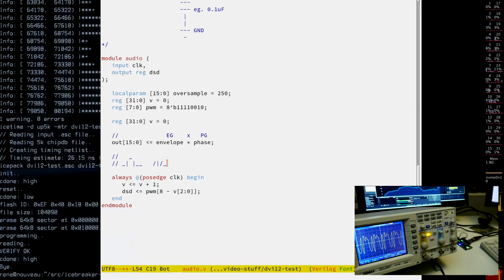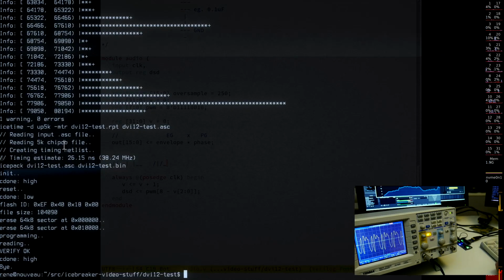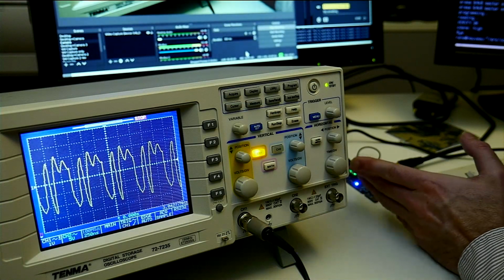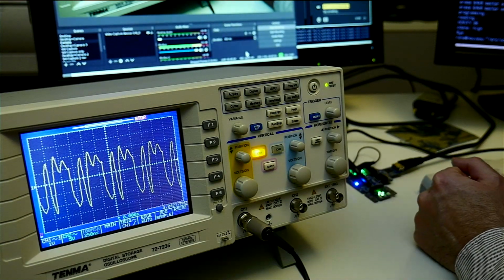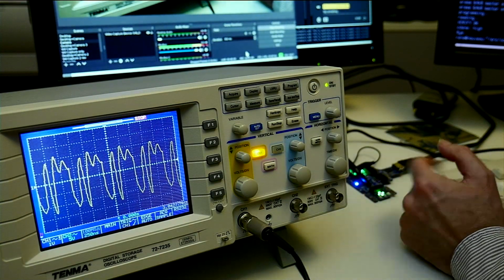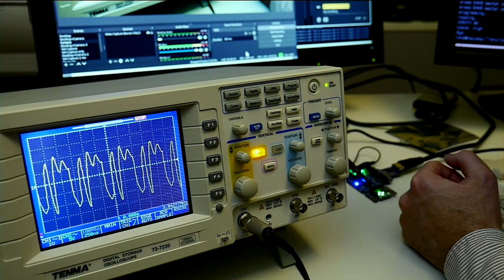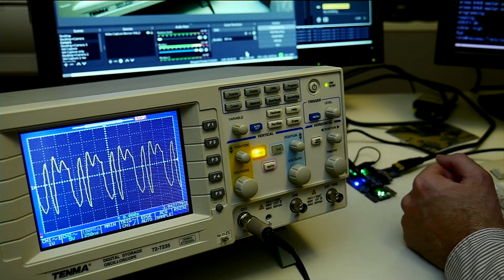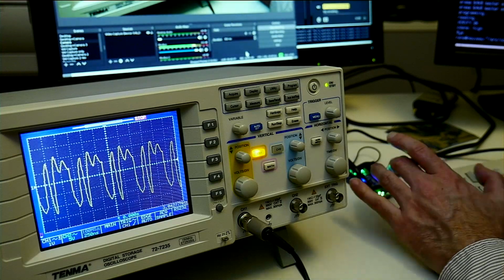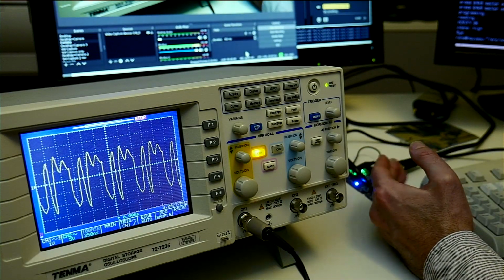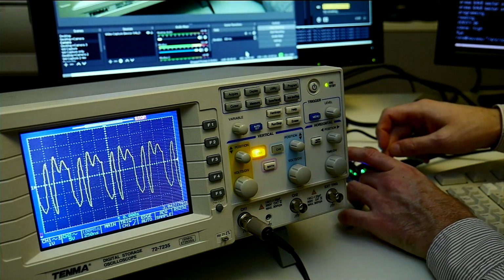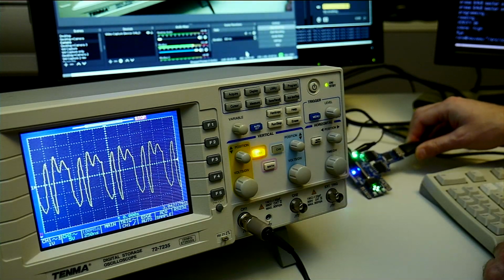We could continue a little bit hooking up here, but the thing is, if I now get out some more electronic stuff and hook up some headphone to get some sound out, of course you should not really do that too much. Theoretically, we should also have some driver, not to connect this directly to the FPGA. The NES emulator people said it's fine. They didn't burn the FPGA yet, but with a resistor it probably shouldn't overload. So probably I will solder a resistor, maybe also break off this PMOD there. This side one is there to break off.